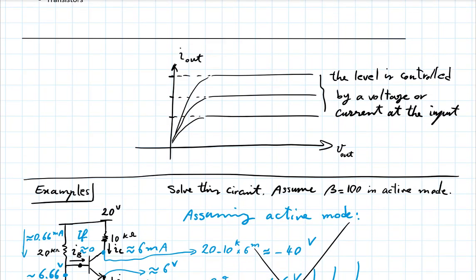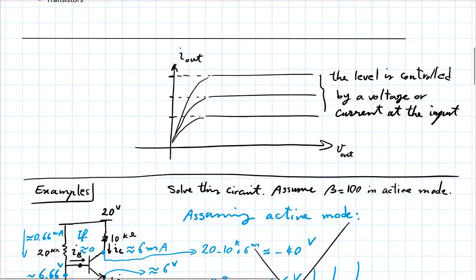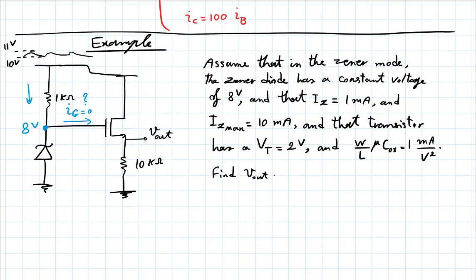It has to do with whether this V out, for instance, in this case, would be your drain source voltage. If that drain source voltage is positive, you would be in saturation, which is the equivalent of the active mode, if it's greater than a certain threshold. Let's assume that that is the case.